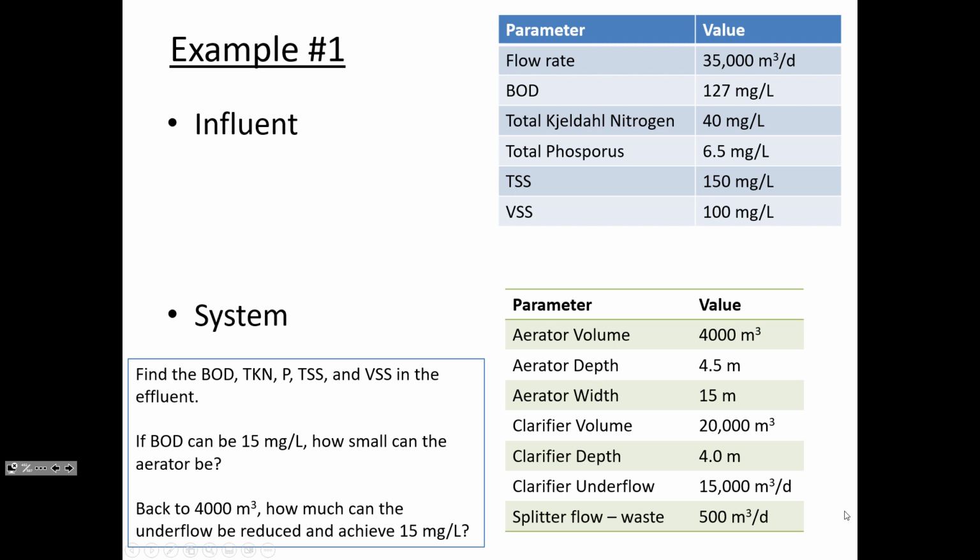We are going to start from scratch. You've just opened a pre-built model to verify that the program worked, and we may come back to that later, but we're going to start from just a white page, blank screen, and put together secondary treatment in a wastewater treatment plant. And you can see that I've got the values defined here of the flow rate, the BOD, and so on. So the chemical and biological characteristics.